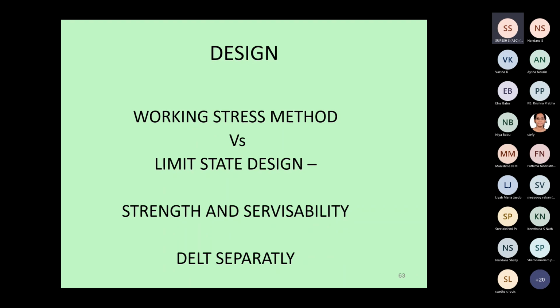95% of the samples will have excess of that value. 5% can fall below. So that is why in the seismic load design we have discussed, we design the structure for a smaller loading, taking into account ductility, overstrength, etc. This overstrength comes from this parameter.